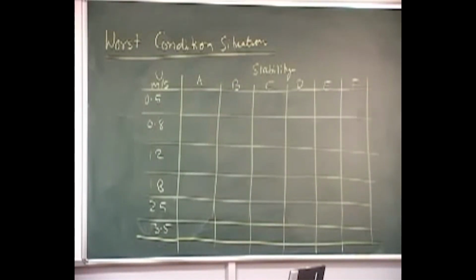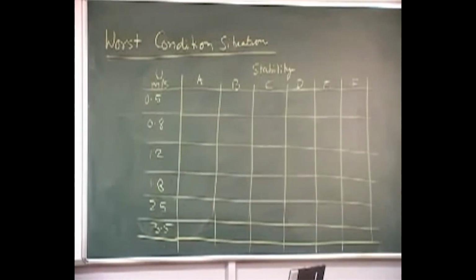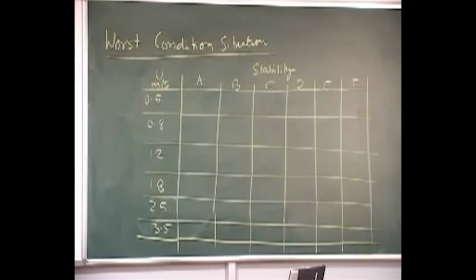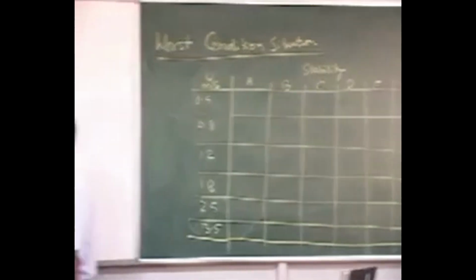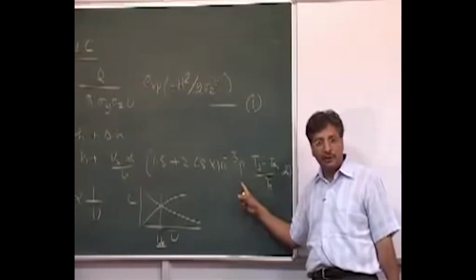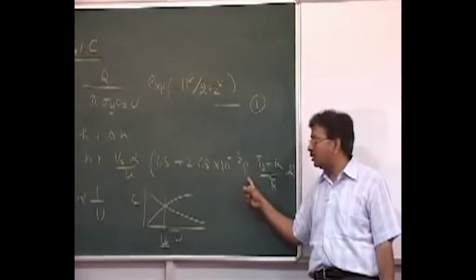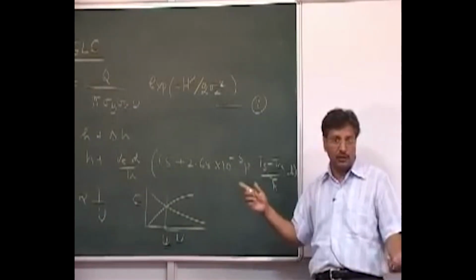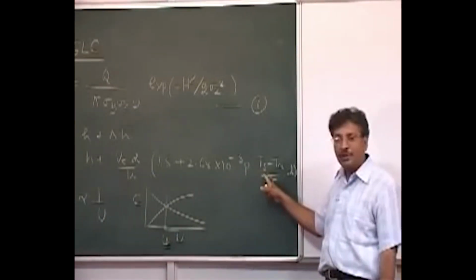A power plant is there, a refinery is there, whether it is existing or proposed, right? If the refinery is going to come, I know about H. First of all, I know the physical stack height. They are going to provide a stack height of 100 meters, let's say. This is fixed, right? Delta H can be variable. How will delta H be variable? We'll see. The pressure can be variable, but this variation again may not be so much because it is close to 1000. This is a parameter which is fixed.